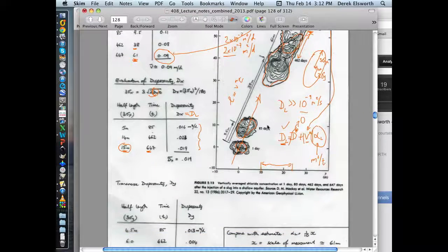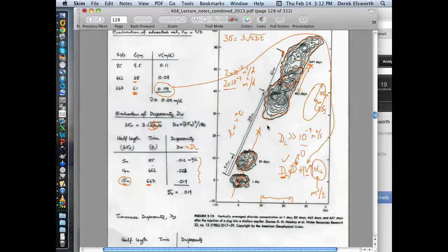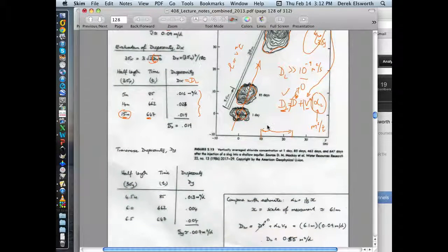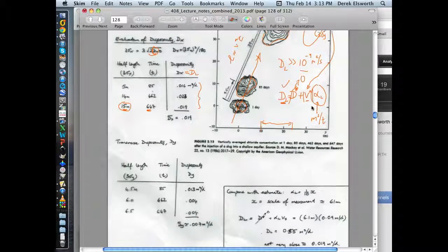Okay? All right. So we've made the point that in aquifers where there's relatively high flow velocities, there's going to be this dispersivity term, and this is going to be still there but completely swamped. In aquifers which have very slow velocity, like clays and shales, then this term, even though it's small, will be significant because this term might be 0, and so it may be the dominant feature.